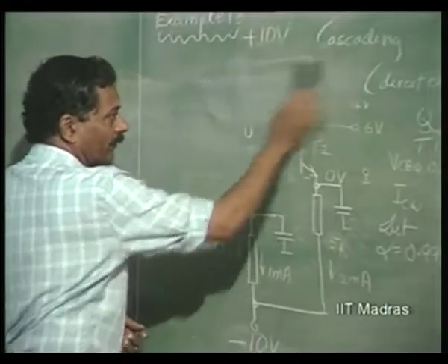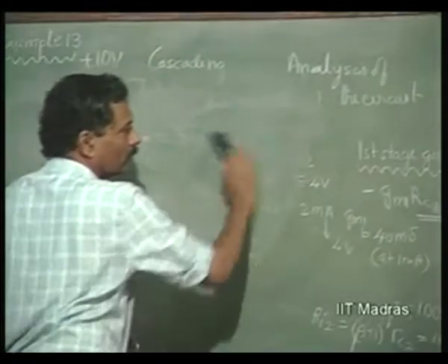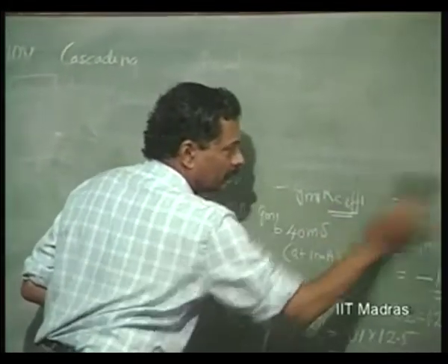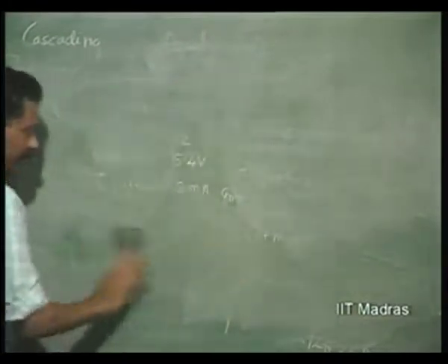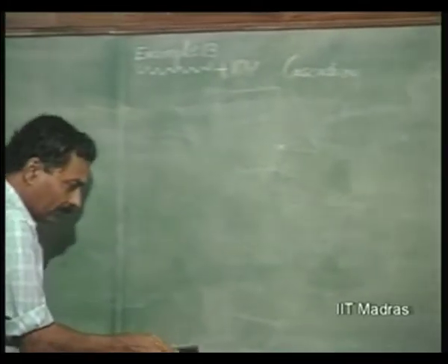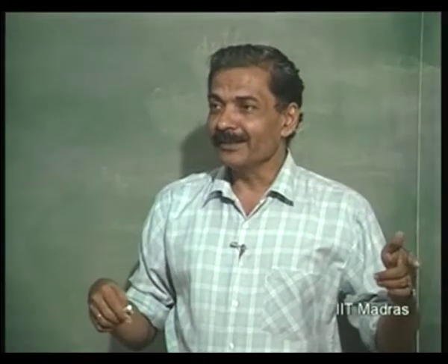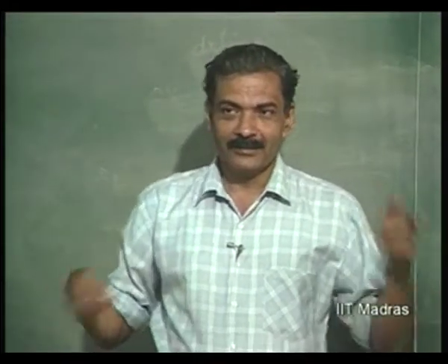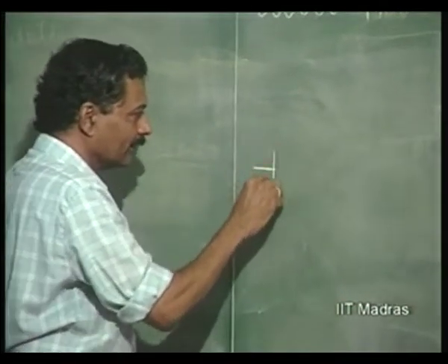These are IC amplifiers. So, we will now see how to get rid of this capacitor, which is huge if you want good low frequency performance. And if you put such a huge value of capacitor, we would like to get rid of drift. So, in one shot, we would like to solve both these problems.